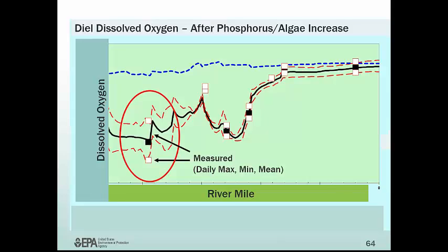So we went back and we let the algae grow up to above what was measured on the periphyton samples. We did not have macrophyte samples, unfortunately, but we did have that visual inspection, and we knew there was a pretty large biomass of macrophytes. So we let the algae grow, if you will, and as expected, that makes the DO swing start to match the measurements. So this can get pretty messy in terms of the information you have, the information you do not have, and potentially even measurement error, as we talked about with the velocity example.